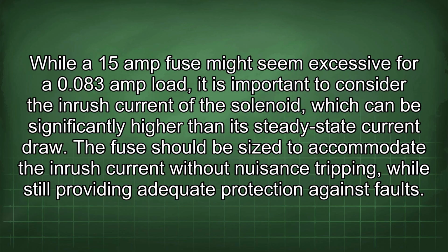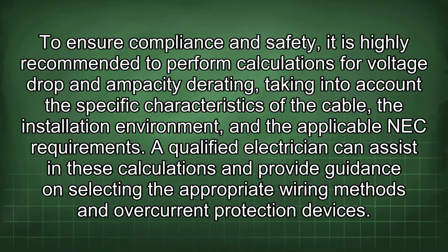The fuse should be sized to accommodate the inrush current without nuisance tripping, while still providing adequate protection against faults. To ensure compliance and safety, it is highly recommended to perform calculations for voltage drop and ampacity rating, taking into account the specific characteristics of the cable, the installation environment, and the applicable NEC requirements. A qualified electrician can assist in these calculations and provide guidance on selecting the appropriate wiring methods and overcurrent protection